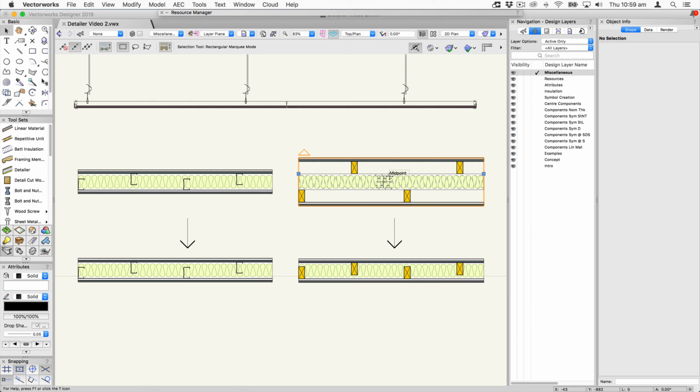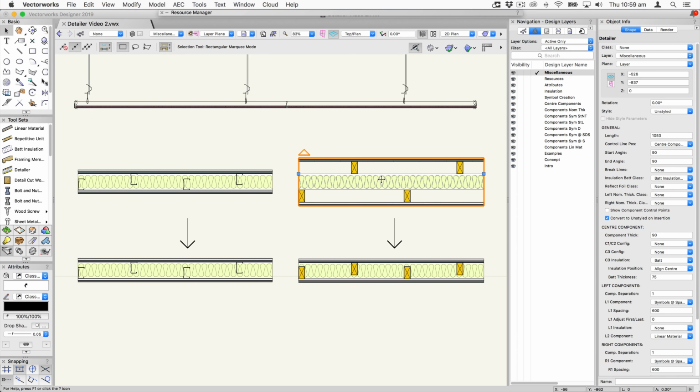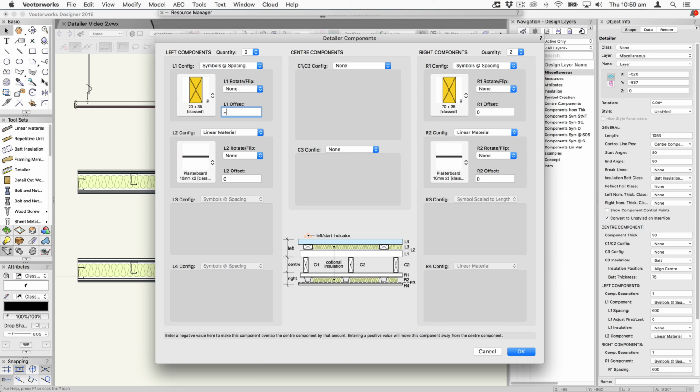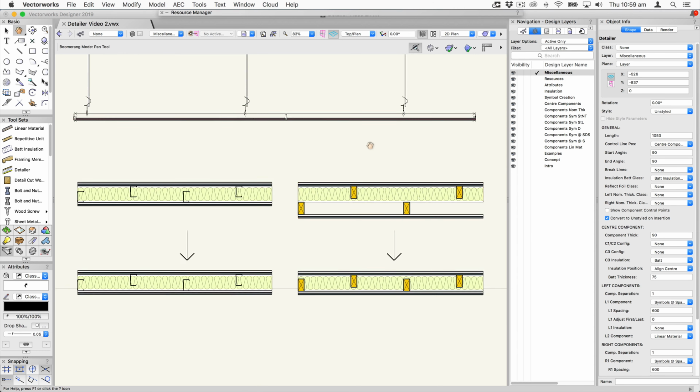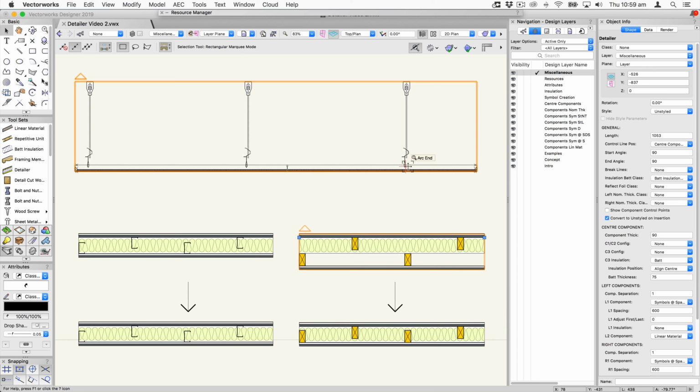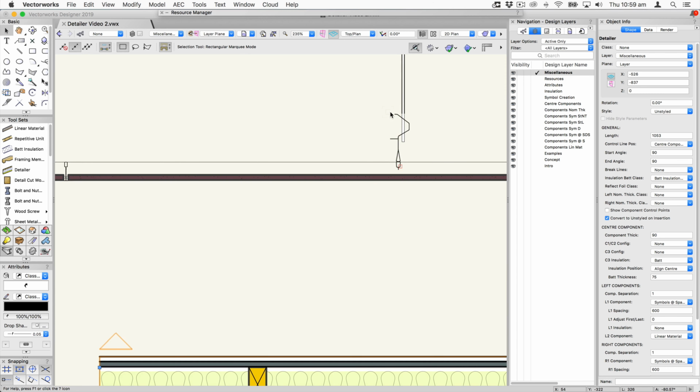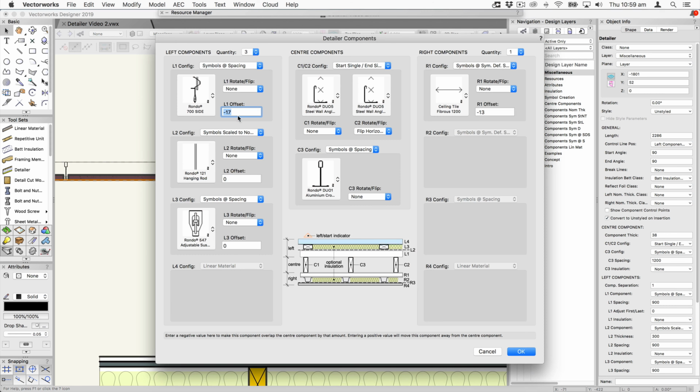And it's a similar situation here. The studs are just timber studs, but I think these are 70 millimeters, so I'll just do one of these. If I do minus 70, you're going to see that it pushes that back down. So that is the way that you can overlap things, and that's also been used in this one here, where you want this symbol, or this component, which comes down to here, to overlap this supporting member here. And if we have a look at that, you'll see that it's offset by minus 17 millimeters to enable it to appear overlapped over this bar.